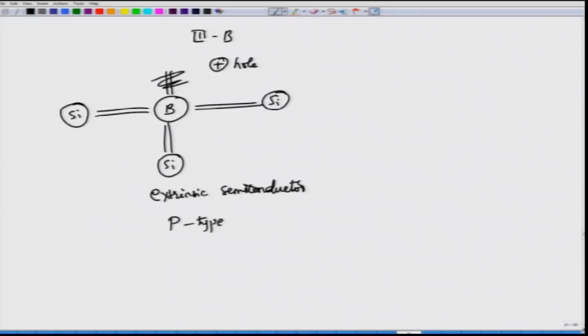The concentration of the p type semiconductor material is roughly equal to Na, where Na corresponds to acceptor ions, because boron accepts these 3 and does not accept the other valence electron. But because it is bonded to this one, it will not be possible for it to just detach from itself.